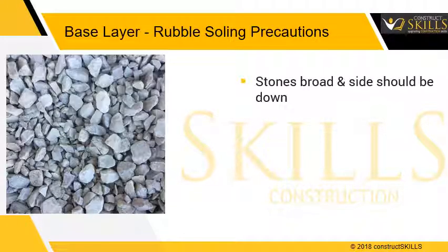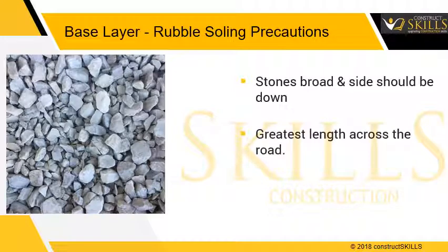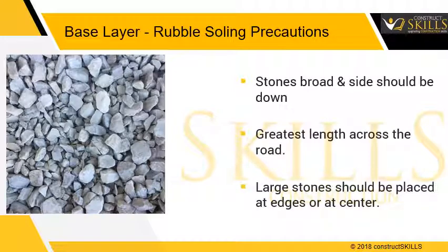Rubble soling precautions. The stone's broadest side should be downward and its greatest length across the road. Large stones should be placed at the edges or at the center.